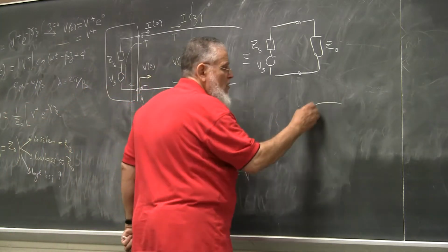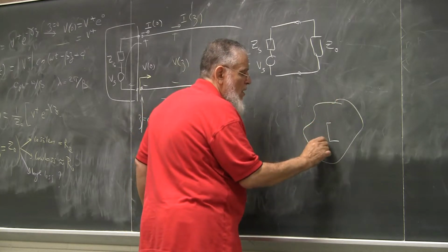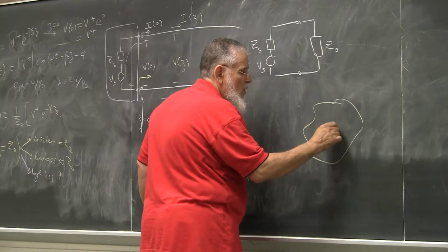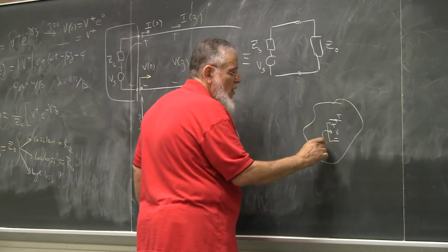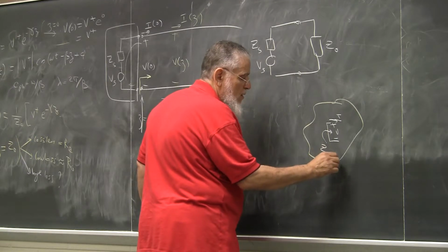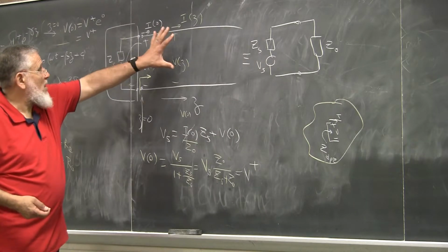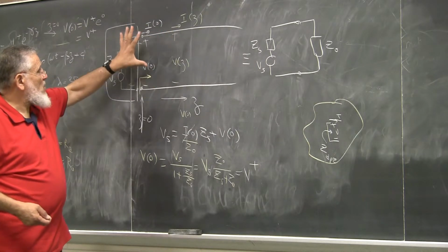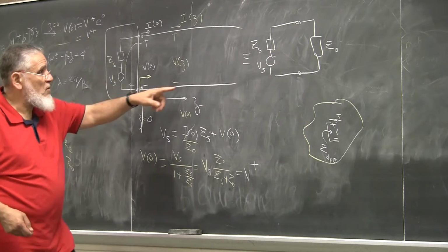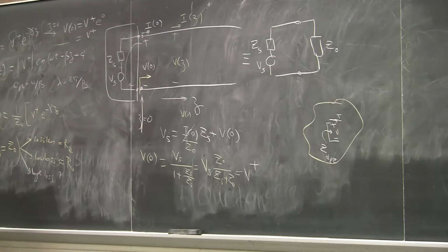You go to any circuit, no matter how complicated it is, and you look at the voltage and the current within the network, you get the driving point impedance. So if I look at the transmission line, the input impedance here, or the driving point impedance, is actually Z0, at Z is equal to 0. But you see, the driving point impedance anywhere on the line is Z0. It's not just at the input side.